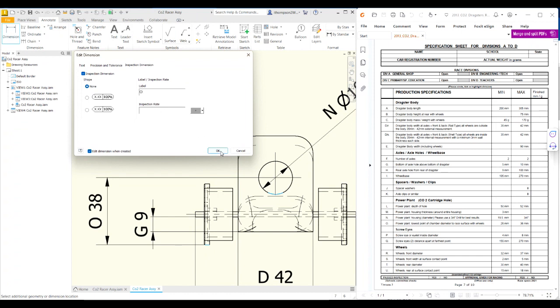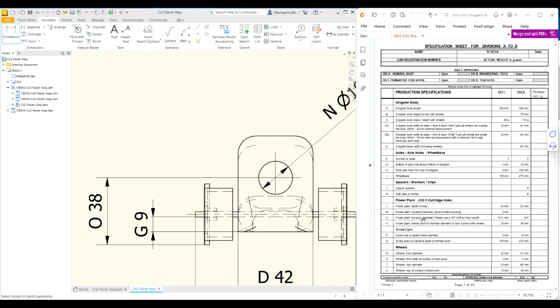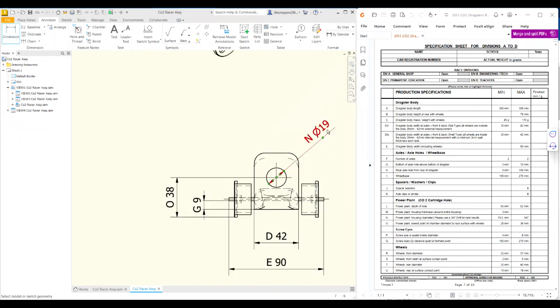Well, capital O. Okay, and I guess when we actually fill this in over here, what we're going to do is take that diameter there, or that radius, which is going to be 9.5, half of 19. So that radius is 9.5. Take 9.5 off that, and what's that going to give us? 38 minus 9.5. Just using my calculator, that gives me 28.5. So this distance here is actually 28.5, which is good. That's within spec.